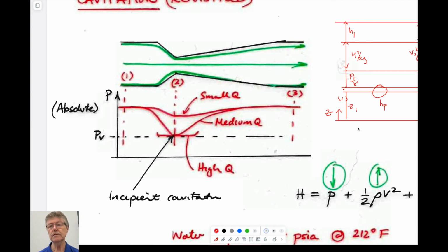And so what we will define is this EGL, an energy grade line. And one other thing we have is a hydraulic grade line, which is just the sum of the pressures and the elevations, not the velocities. In this particular case, we know that if this pipe has the same areas upstream and downstream, then by definition, from continuity, the velocities have to be the same.